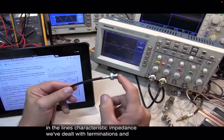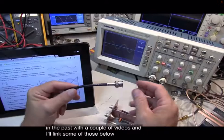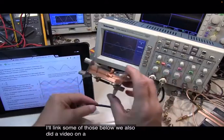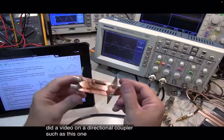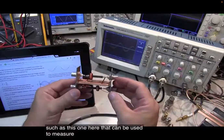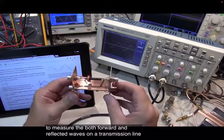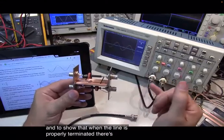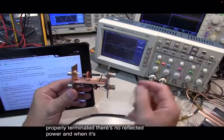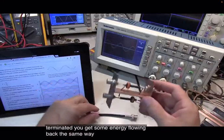We've dealt with terminations in the past with a couple of videos, and I'll link some of those below. We also did a video on a directional coupler, such as this one here, that can be used to measure both the forward and reflected waves on a transmission line, and to show that when the line is properly terminated, there's no reflected power, and when it's improperly terminated, you get some energy flowing back the other way.